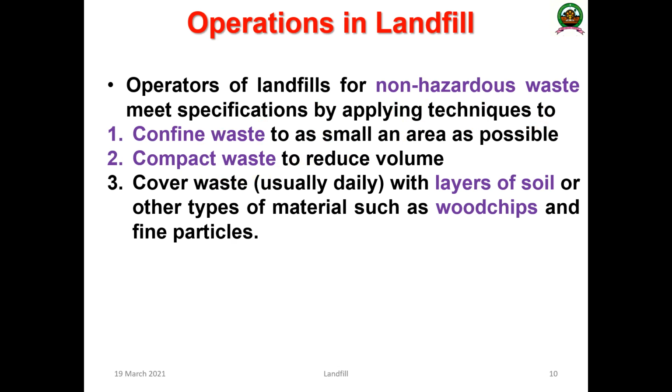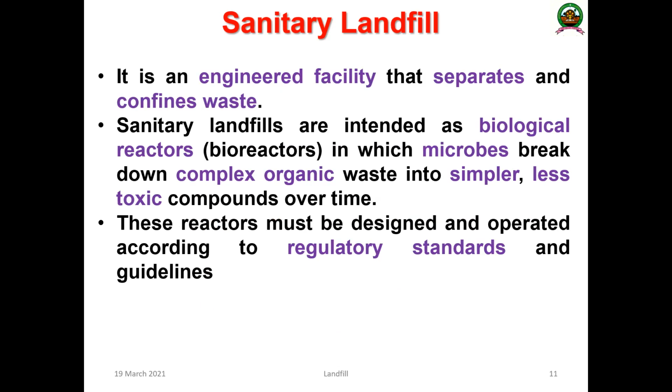Then cover the waste. Every day you need to cover it with layers of soil or other types of material such as wood chips or fine particles. So that is very, very important. So these are the three important operations in the landfill.